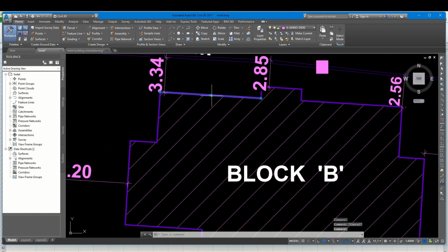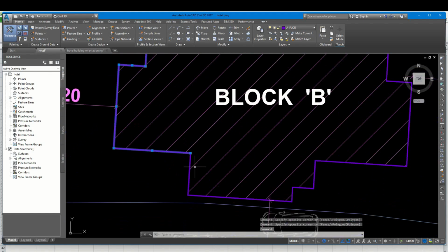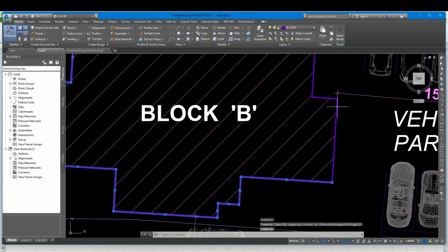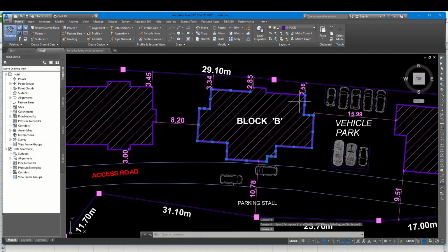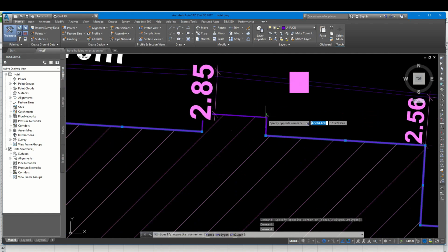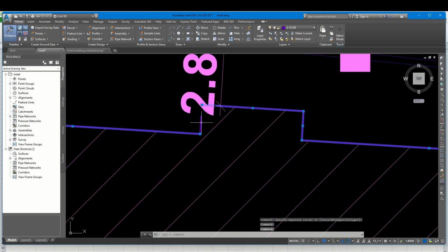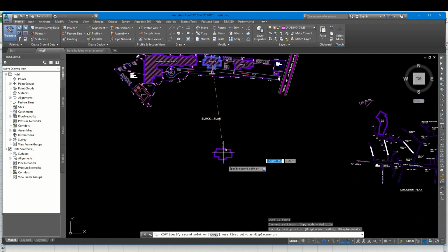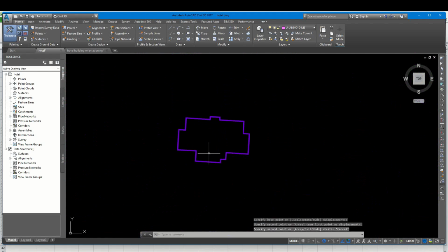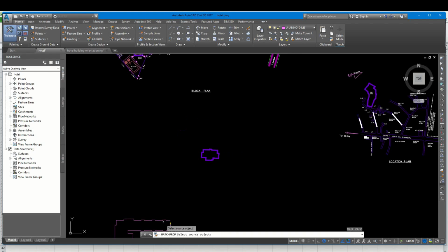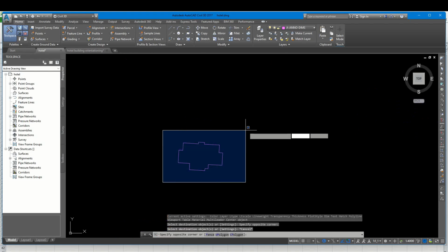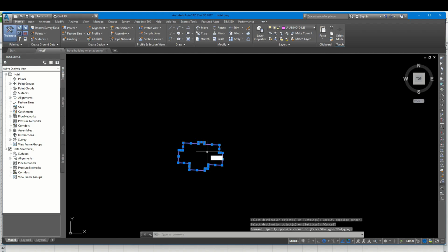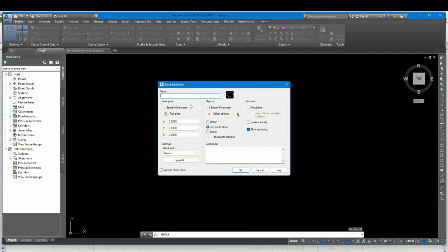I will be taking this block, or the block line for the guest house. If you can study this properly and get the detail of this, it means wherever site you are going, you'll be able to orientate it, be it however large the site looks. It is a starting point. This is the starting point. Let me match the line, the building block, and I will make this a single entity block. Let me just call this the guest house.